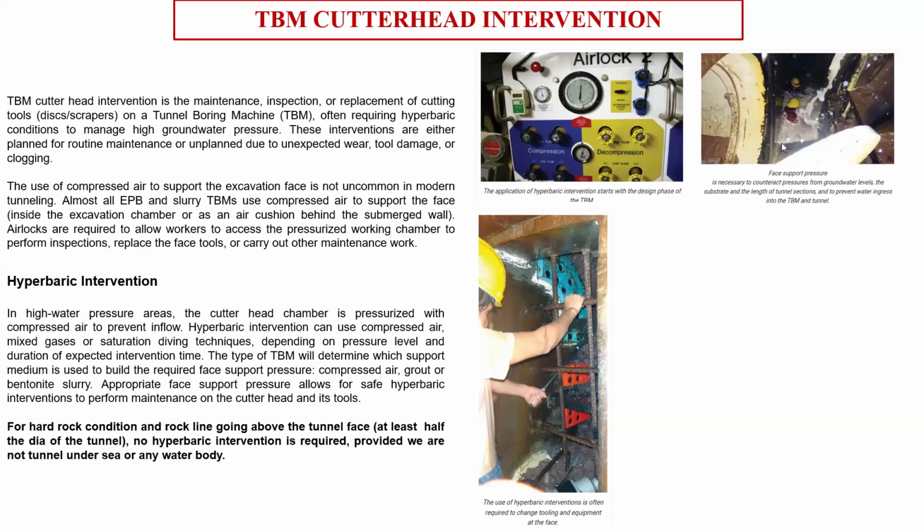There is a grout called PU grout. The PU grout is a very flowing type of grout. It easily flows, it has a very high consistency and a very high penetration rate through the ground, and it applies a pressure, and through this pressure we try to lift the segment as much as possible. And after that we did additional grouting to close all the joints between the segments.